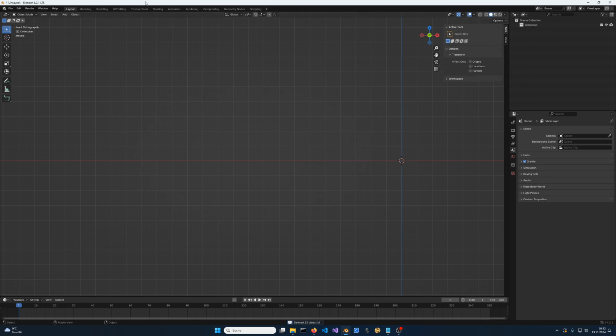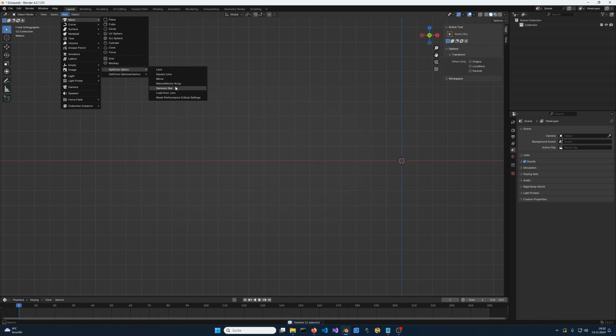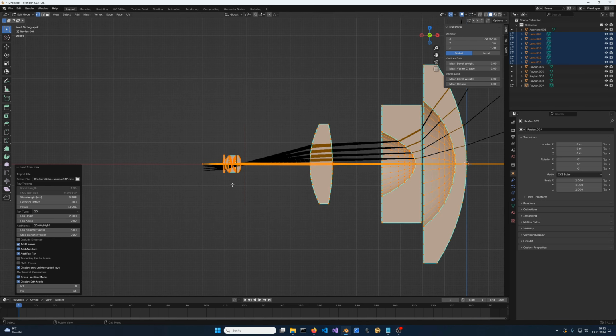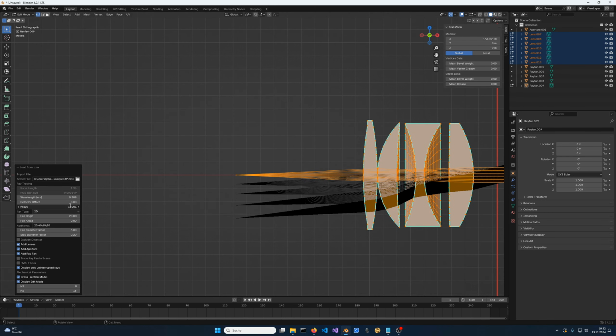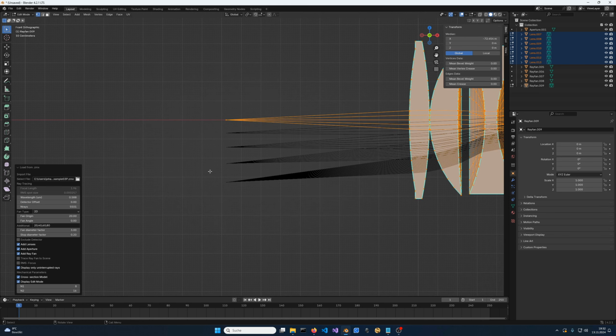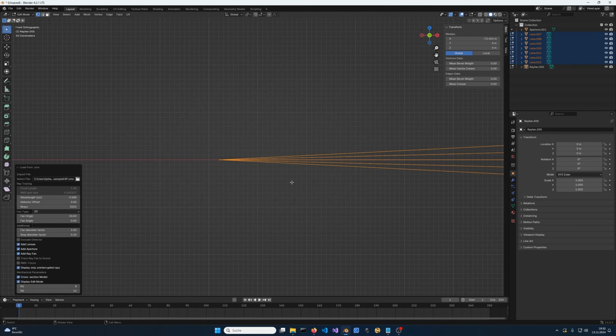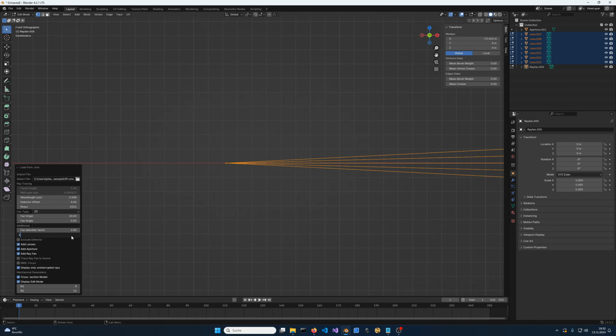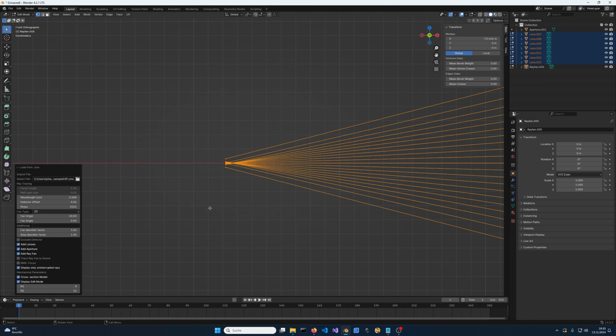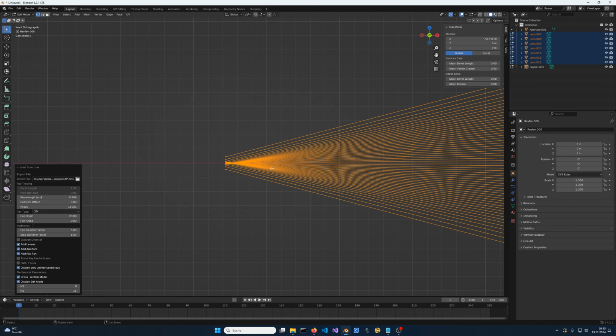Right, I'm going to have to delete everything again to get the operator back. This would actually have been a good opportunity to use the reset performance critical settings feature. However, here we are. I will reduce the number of rays again. Oops, wrong field. I will delete the additional angles, make this a bit quicker. And I will increase the stop size to its nominal value again. And now we can allow some larger number of rays again.